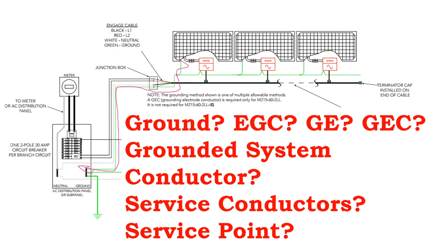The neutral wire, this neutral, there's one point on the system where that neutral is connected to ground, and that gives that neutral a 0 reference point. Whereas the equipment ground system carries that electricity back to its 0 voltage potential during a fault, the neutral wire is what carries it back under normal operation and then to ground.